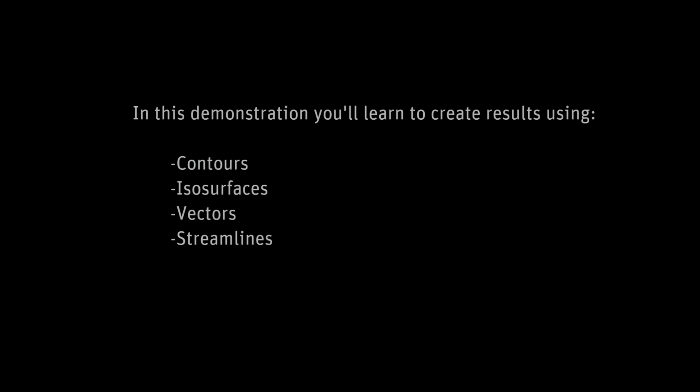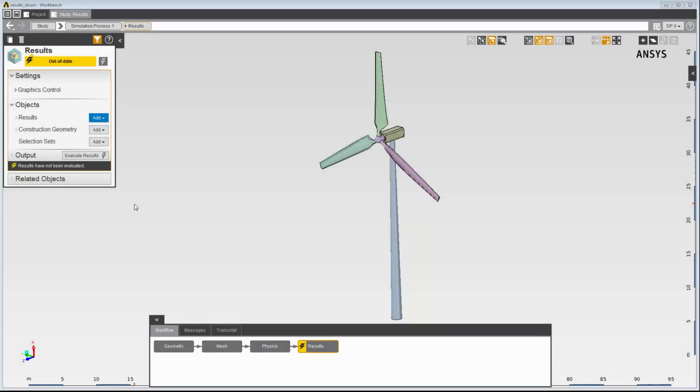In this demonstration, you'll learn to create results objects in Ansys AIM. You can create contours, isosurfaces, vectors, and streamlines to process numerical and graphical visualizations of your simulation physics. I'll use a wind turbine geometry to create results objects to visualize the interaction between the air and the wind turbine. For the solved structural simulation, I'll start by adding a predefined contour result to visualize the equivalent stress on the wind turbine due to the force of the wind acting on the blades.